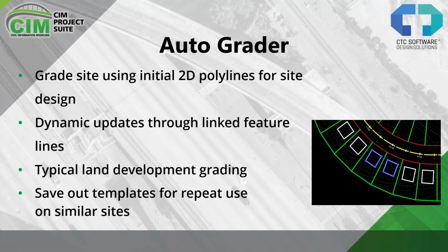Okay, AutoGrader. Initially, you don't really grade this site using 2D lines. You will lay it out using 2D lines. And then we can pick those in the subdivision, as you can see from the little screenshot there, to run our AutoGrader from. Now, some of this takes some setup. You have to be consistent with your layering and your methodology.